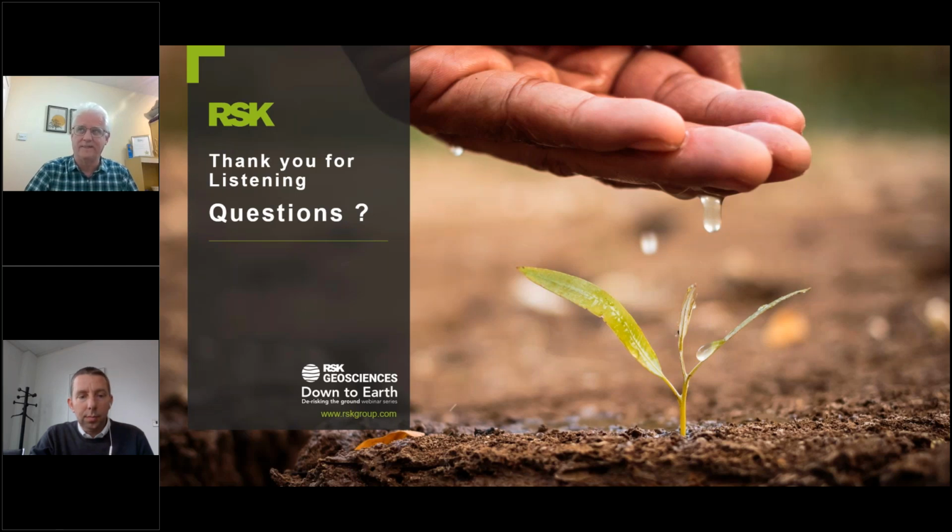So I think the NHBC is pretty comprehensive, to be quite honest. But if there was a rare situation where there wasn't a tree identified, then you would have to go down the route of an arboricultural survey, and try and get them to classify it as closely as possible to an existing tree. You've got your broadleaf trees, and an arboriculturist would give an assessment.